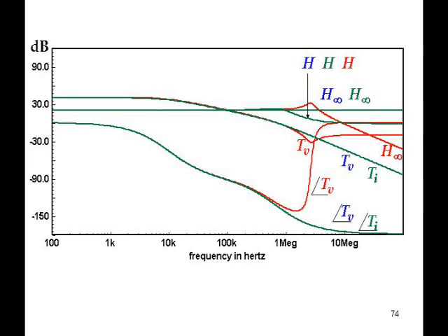And the phase angle and the magnitude are both completely different at higher frequencies from what they were at the ideal voltage injection point. Now this is another warning that you have to be very careful where you do the injection if you're going to get the answer that you want to get.